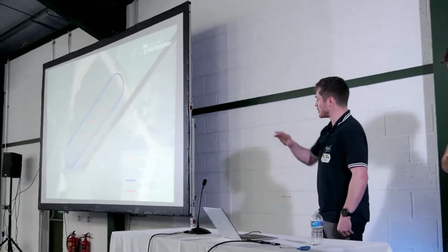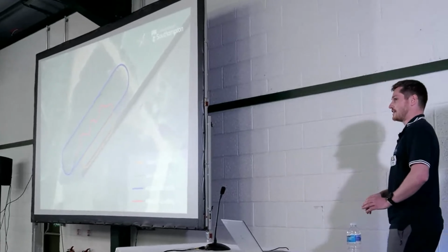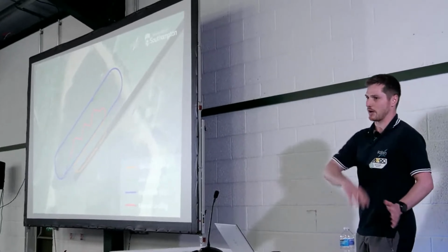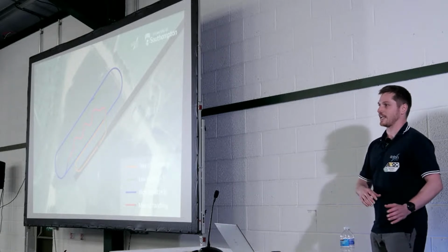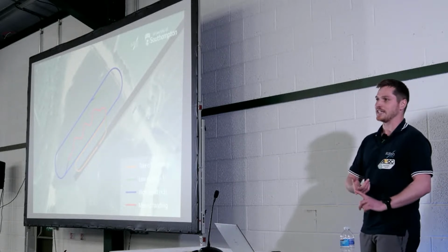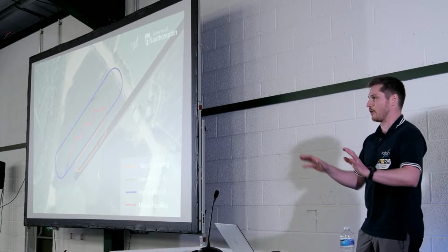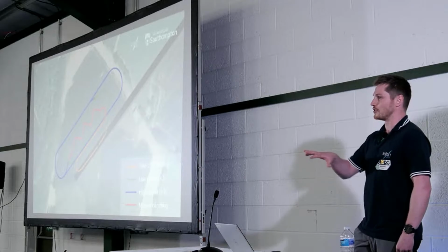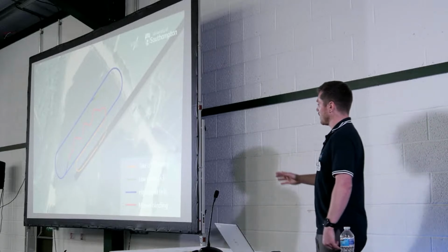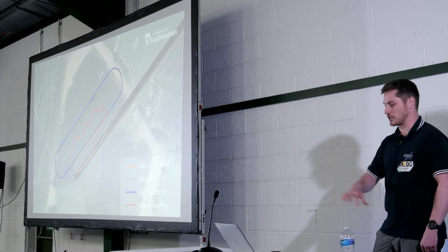Following that, we do some manual handling, and this can be quite an exciting moment of the flight test, because it turns out fly-by-wire A and Auto are very good at masking trim conditions and asymmetric lifting on the wings. And so if you do have an asymmetric flap deployment or retract, when you switch to manual, the pilot has to work a little bit hard to correct that. And we do the manual handling to see how responsive the aircraft is from a pilot's perspective.